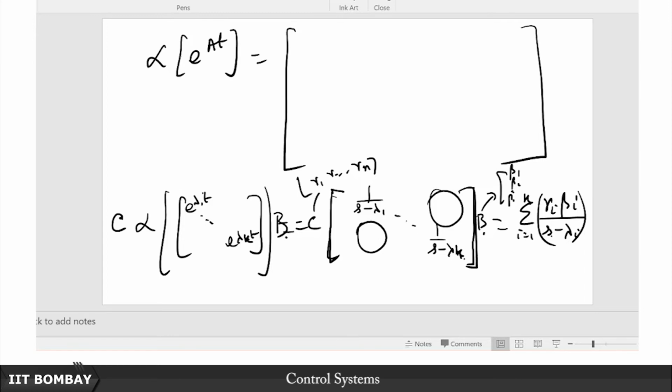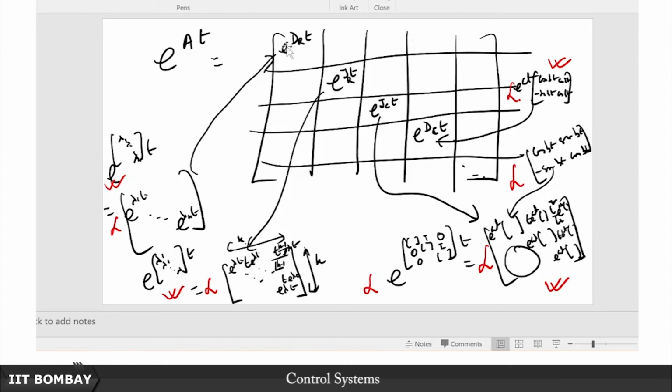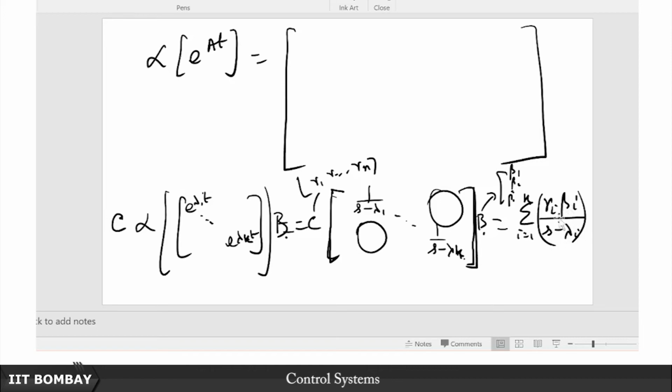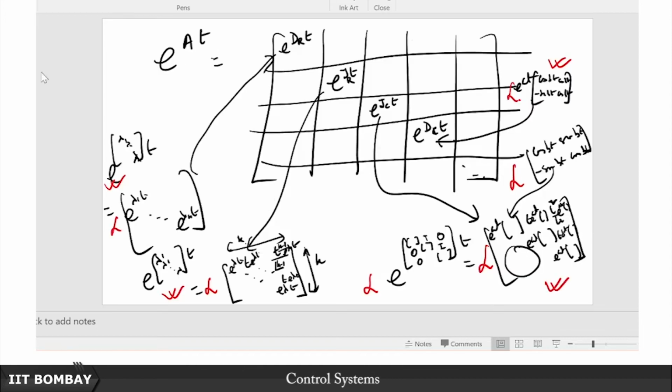So if you take the LCM of k minus 1 first order factors, the denominator polynomial will be of degree k minus 1. So if you now go back to that big matrix, from this diagonal block here, what does it entail? It exactly entails that if any one of the first k entries of B or the first k entries of C is 0, then you will be missing out that particular mode from the transfer function, and therefore this k cross k block, this determinant. Note that since it's a block diagonal form, the determinant is just the product of these individual determinants. No?